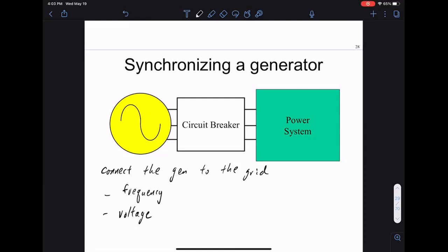That's why we want the frequency to be very close to 60 Hertz, very close between everything in the grid, so angles don't run away. If it differs by 10 Hertz, the generator blows up almost immediately because the angle goes all over the place, trying to deliver power sometimes and absorb power sometimes. This is unstable behavior for the generator.